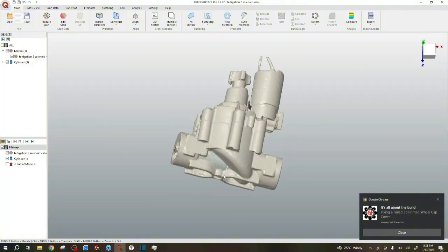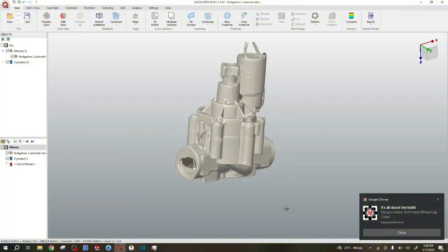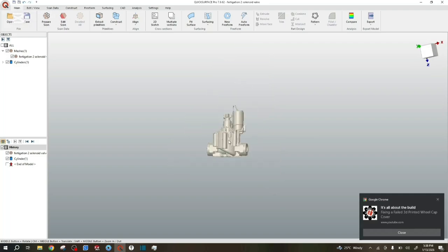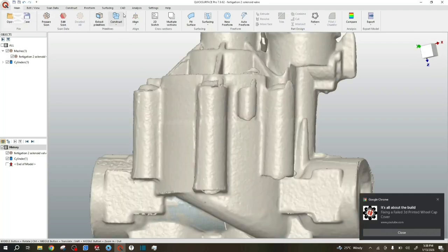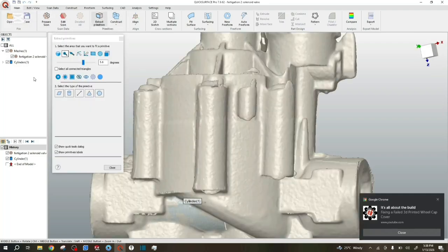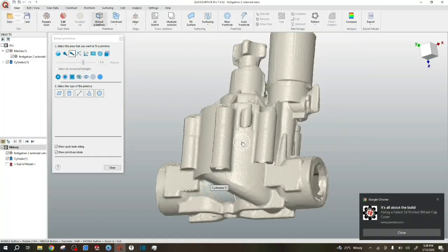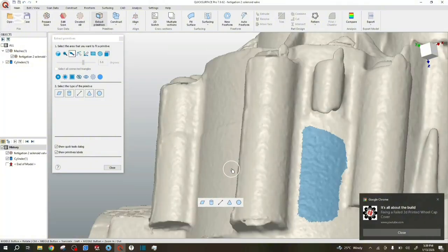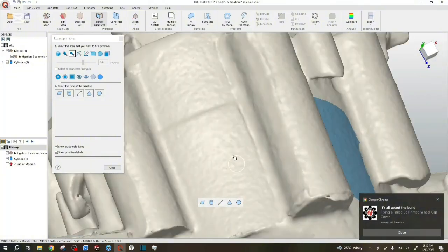The second feature is going to be this big cylinder that we can see over here, sliced over here. We still choose extract primitives, and this time around we're going to use the freehand tool and select this surface there. That's the cylindrical surface, and you can see I'm choosing the lower section because we have a seam over here.